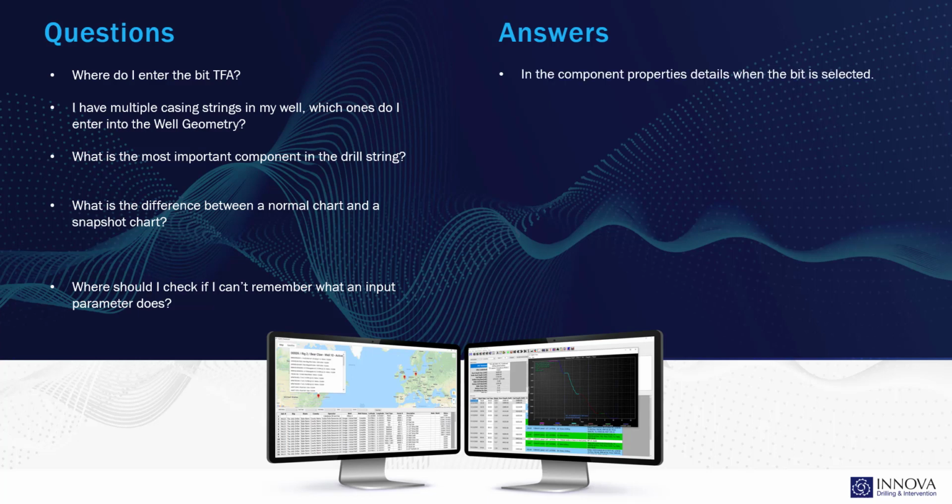The answer is in the component properties details when the bit is selected. So you select your bit in the drill string table, and then you should see in the component details section at the bottom the option to change your TFA.